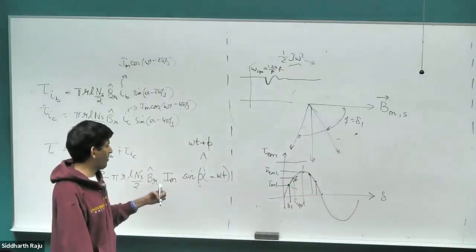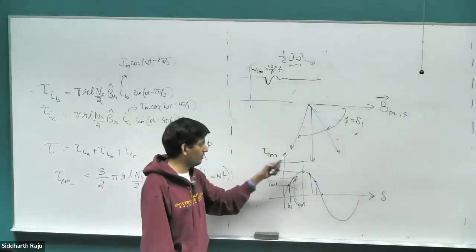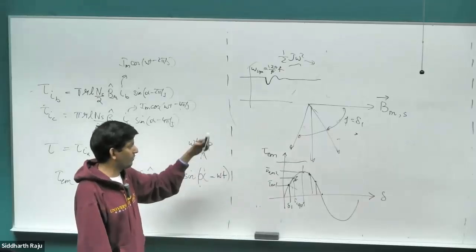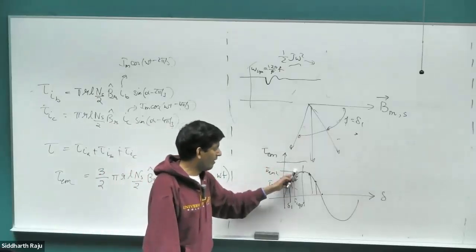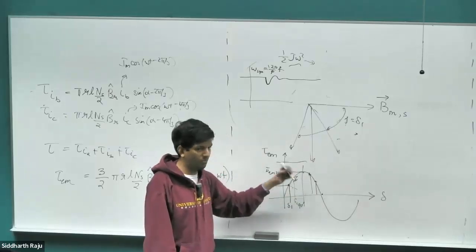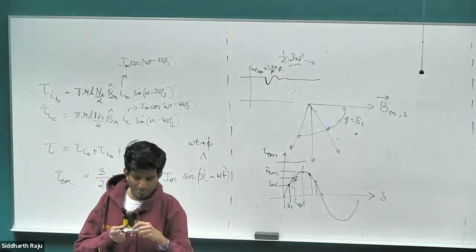Right? So that's what happens in a permanent magnet synchronous motor. Once you reach the peak torque, you still demand more torque. The rotor will come to a stop. And that is a disaster because we haven't dealt with back EMF yet. We'll do it next week. But the back EMF is not present when the rotor is not rotating. So you'll have a huge amount of inrush current and the motor will burn out or your magnets will get demagnetized.